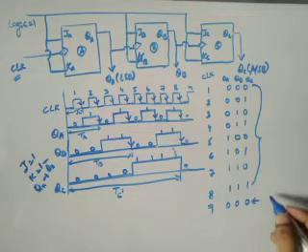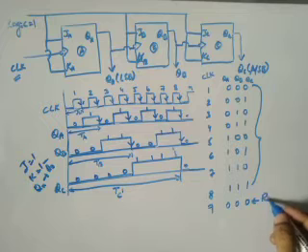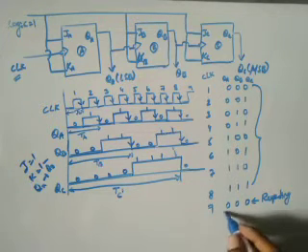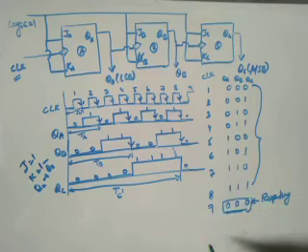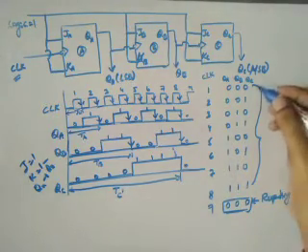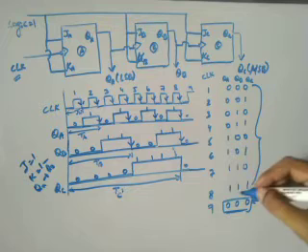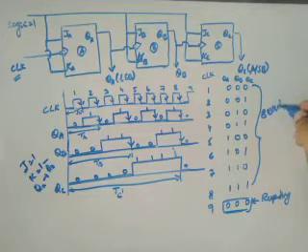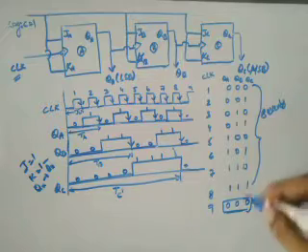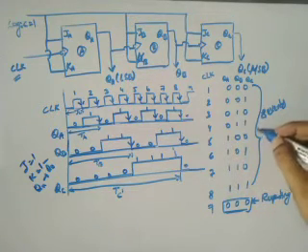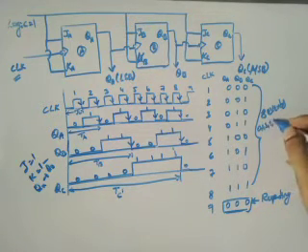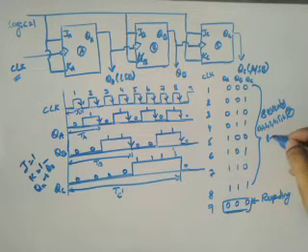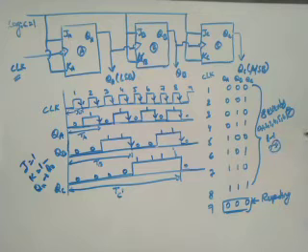After here it is repeating again from 0 0 0. How many events has it counted? It has counted 8 events, 8 states in total. How many numbers is it going to count? From 0 1 2 3 4 5 6 and 7, that is nothing but 8 minus 1, up to 7.